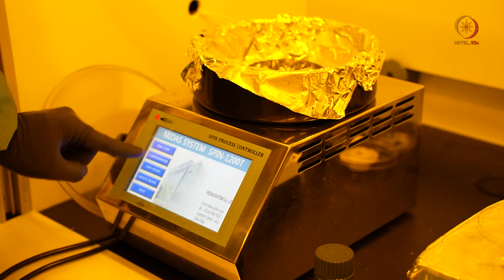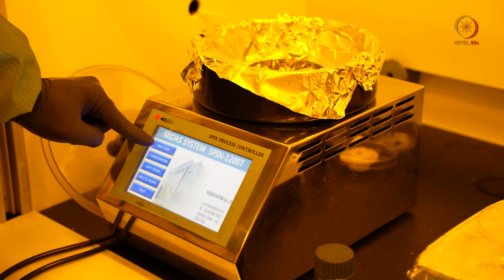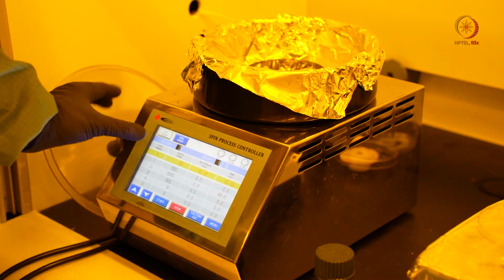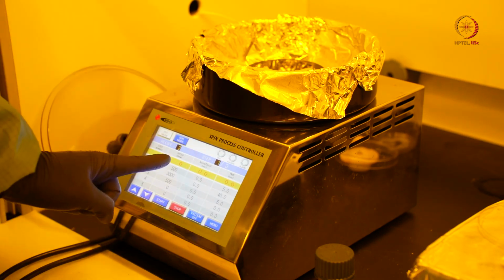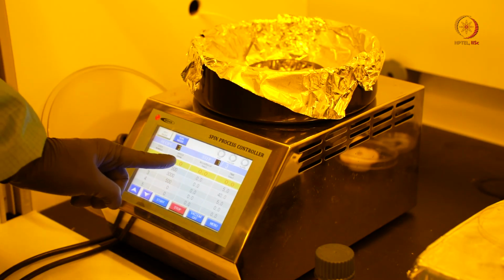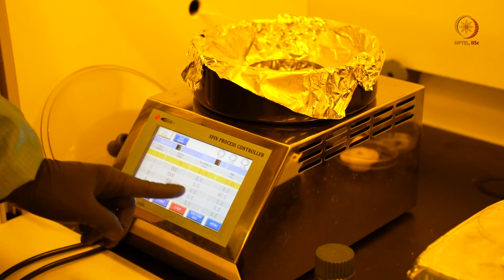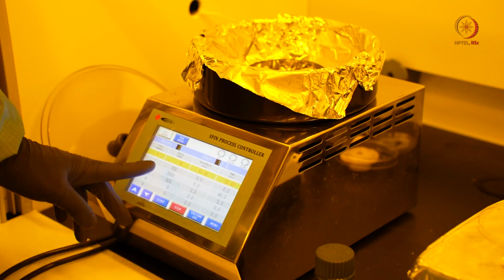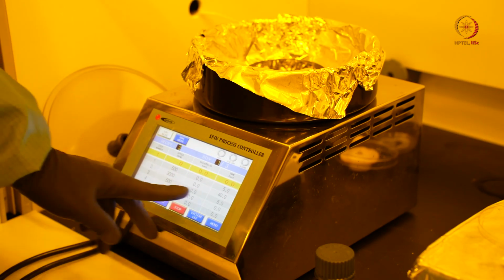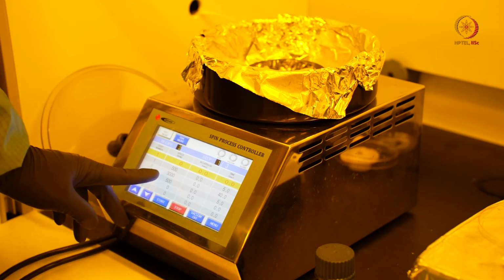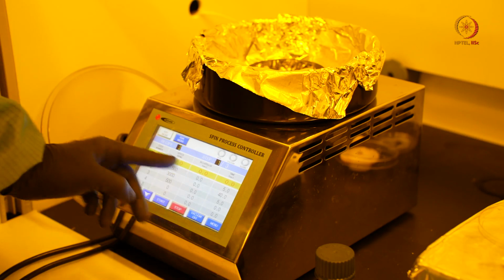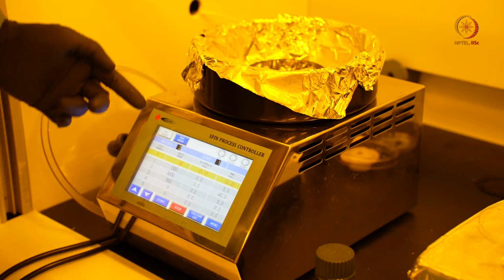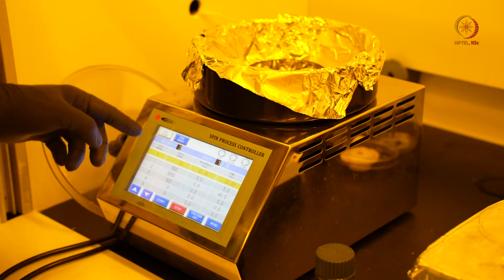So we can go to this run or edit option where you can click it, right? So we already have a recipe set, which means that the rotation will start from stationary speed. It will accelerate to 500 RPM in 5 seconds and stay there. Then followed by rotation at 3000 RPM for 40 seconds, and again deceleration to 500 RPM for 5 seconds, followed by coming back to rest. So this is the recipe, or the speed, at which we have to spin coat this 3012 photoresist.